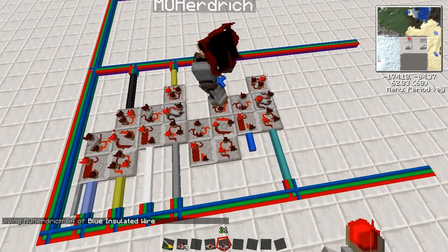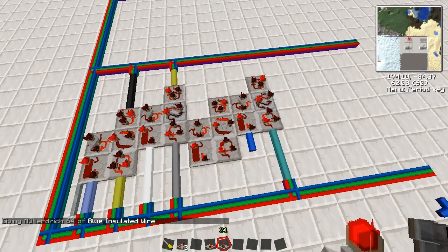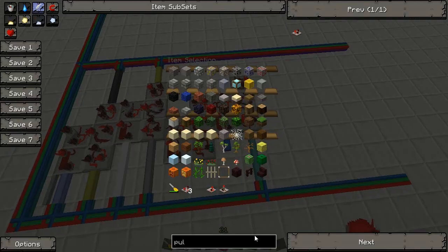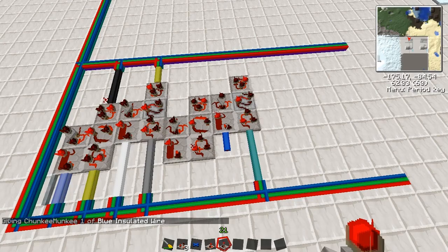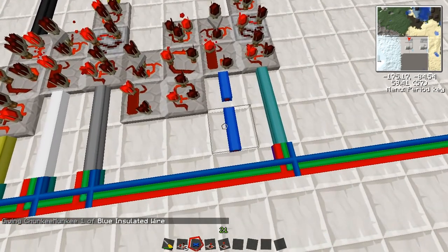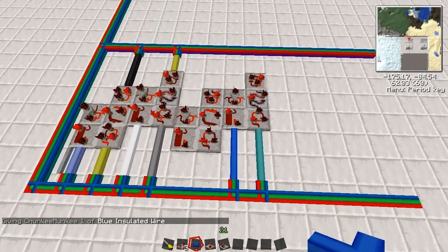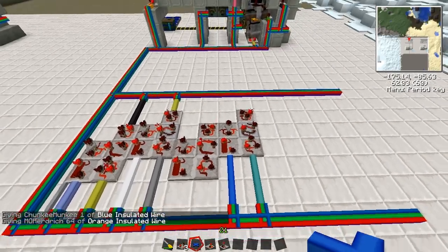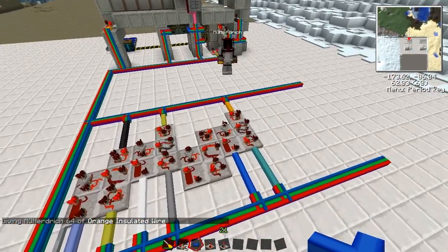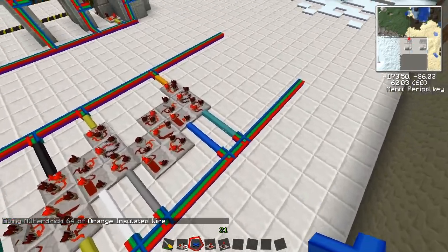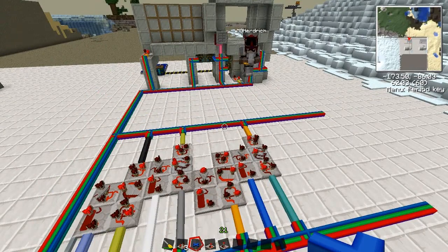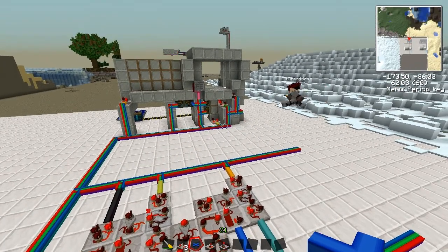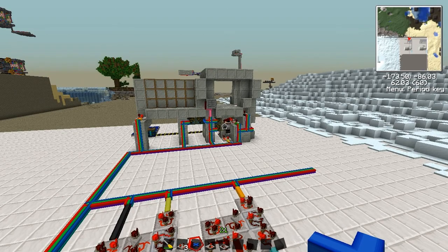The blue cable moves the door over there, so we have to look for the orange signal to stop the process. So when we get a signal from orange, we know the door has completely opened. This switches off this part, and also starts off this part. And this timer will move the platform up, which is red.